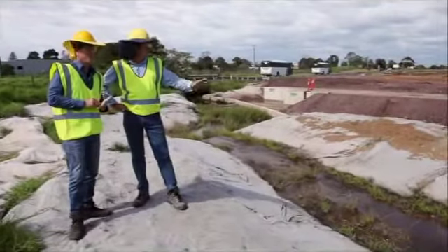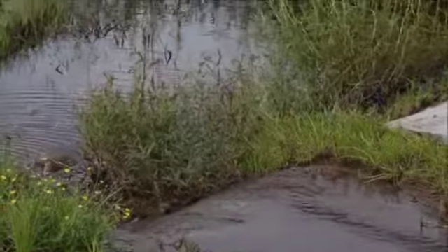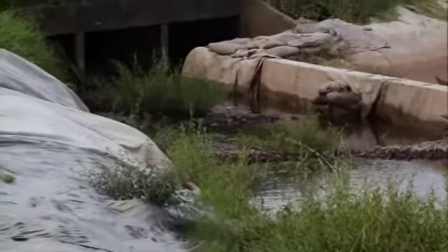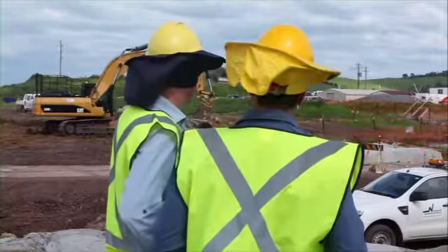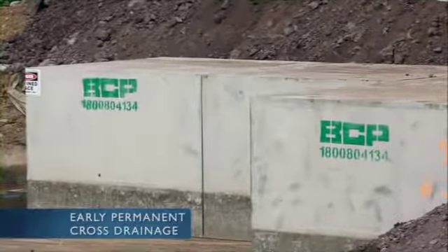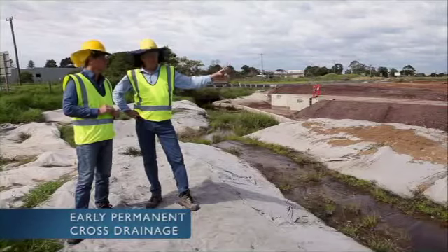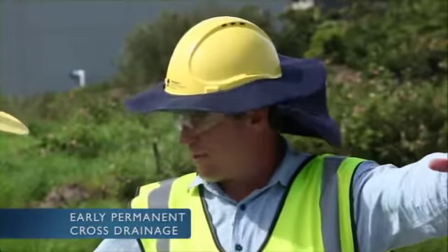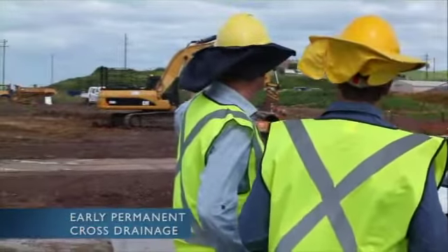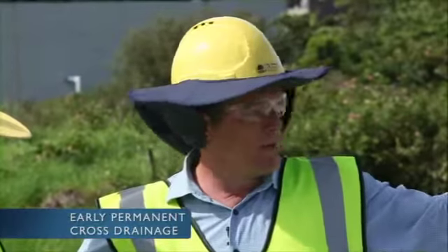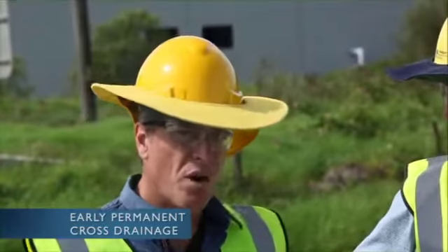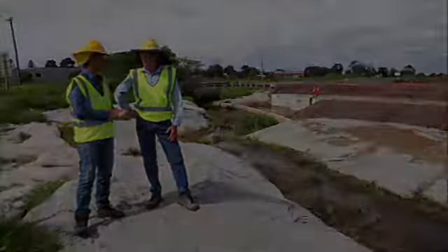Yeah, sure, Pete. What we can see in this location here is obviously our temporary drainage that we've talked about flowing through there. That water is not impacting this construction site you can see here. And what we've got in there is culverts being installed for permanent cross drainage. Now what we want to do in principle is really get that permanent drainage in as early as possible. That means we're going to be able to get that clean water from above the site through the construction site as it continues. What we'll see here over time is those culverts are almost finished. There'll be a series of fill put above that, and then the road pavement will go on top. So it's get the drains in and then complete the road. That's right.